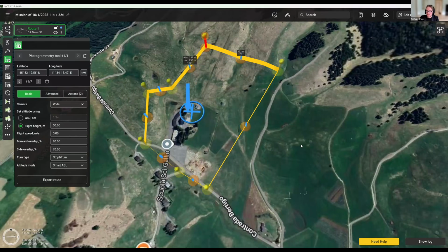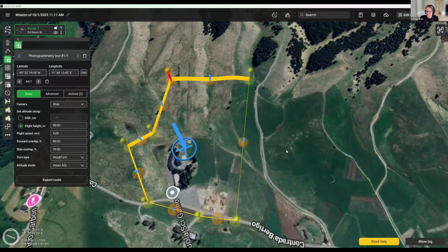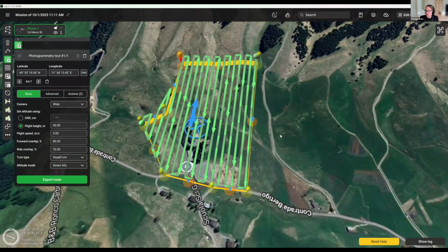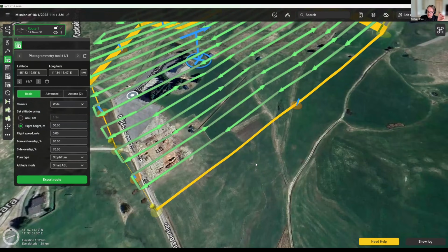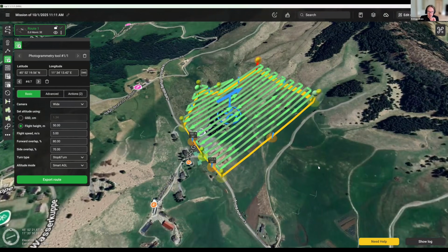But let's say with mini drones, when you're doing some capture, you can fly the default speed of 5 meters, but then when you're doing the data processing, you would need to do probably some rolling shutter compensation. And this is, I believe, available in software like Agisoft Metashape and maybe a few others as well. But one thing I want to show you, because I've been hearing this quite often: in case you want the drone to stop at each position before taking the photo, there's also a way how you can get this done.